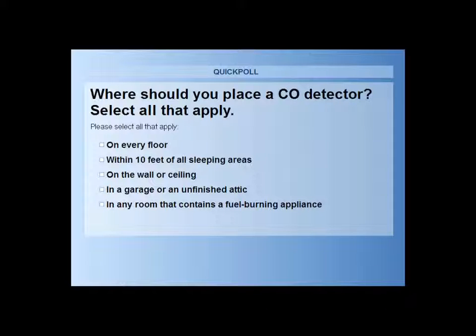Okay, David, all of our detectors have an end of life. In fact, all CO detectors in general have an end of life. The CO cell on our detectors will last for 6 years. After that, they will send a trouble signal to the panel, notifying the central station that they are at end of life, and visually indicate end of life at the detector itself. The audible portion depends on which detector you're talking about. Our i4 combination detector, after 30 days of sending that trouble signal to the panel, will actually audibly chirp, to annoy the homeowner and let them know that it's no longer detecting CO. In the case of the CO1224T, it does not chirp. It just visually indicates and sends a signal to the panel.